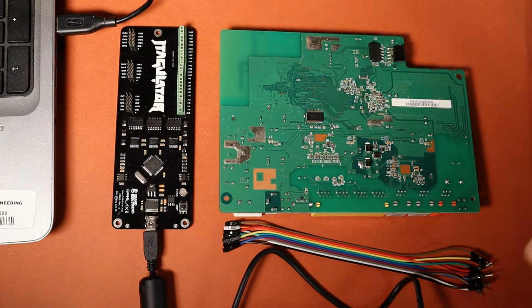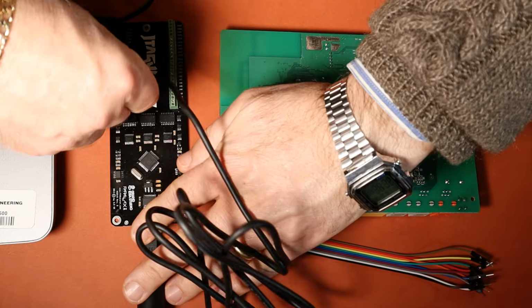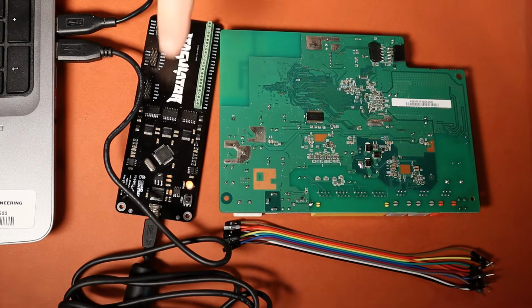First of all, we connect the Jtagulator board to a PC using the USB interface. This powers up the board. In the previous episode of this series, I gave some more detailed information on how to access the serial device on our Linux box. So if something is not clear, please take a look at the previous episode, link in the description below. We have to use a terminal emulator like PuTTY to talk to the Jtagulator board.